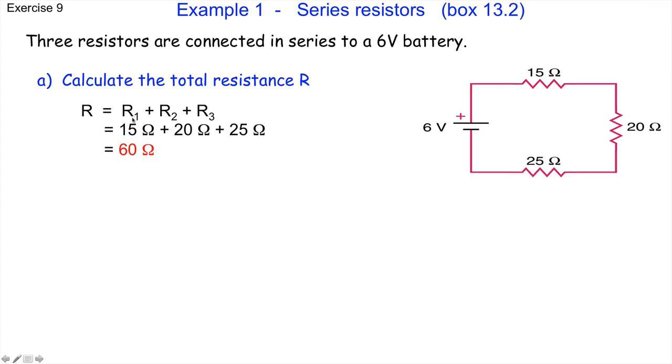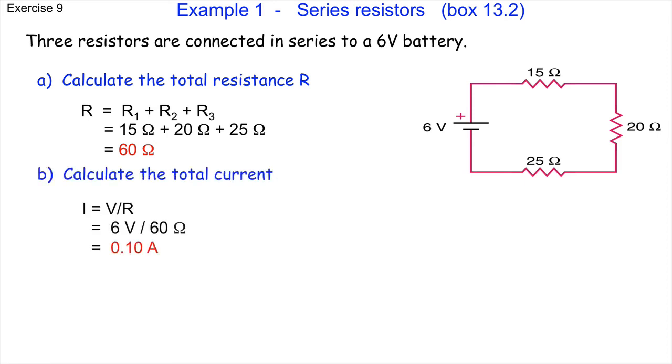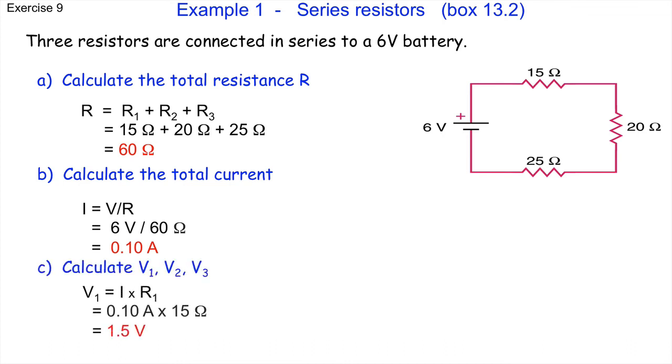We already solved this, remember. To start, resistance in series, because this is series, you just simply add the individual resistances. Then the total current is just whatever total voltage you get, divided by the total resistance, or the equivalent resistance. In a series you can call it the total resistance because you add them all, but in a parallel connection it's better to call it R equivalent.